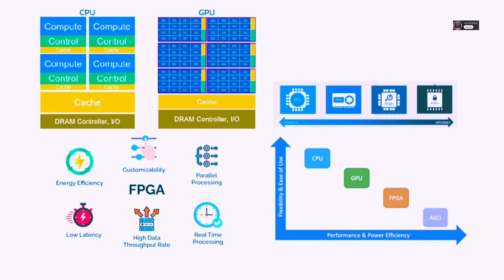Because the FPGA's logic can be reconfigured in the field via a software update, essentially, it is inherently more future-proof against changing requirements or evolving standards. So like if a new encryption algorithm becomes mandatory or a 5G protocol gets an update, you can potentially update the FPGA logic to support it. An ASIC, designed and fabricated today for a specific fixed standard, well, the moment that standard changes significantly, that ASIC might become partially or wholly obsolete. It has zero flexibility. You can actually see that exact evolution play out really clearly in one specific area.